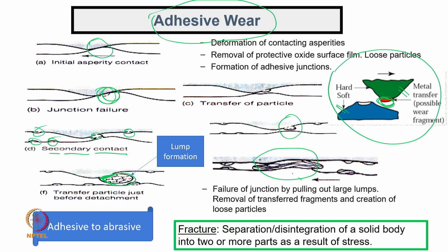So, that is, of course, a characteristic of adhesive wear also. If we get plate-form debris, we say there are more chances of adhesive wear. There is also a possibility that it leads from adhesive wear to abrasive wear. Now, I say that this is a phenomenon happening in adhesive wear, but the particle is coming out from the surface itself. Even though initially it is getting transferred, with no net loss, finally, as the size increases, the particle will get separated